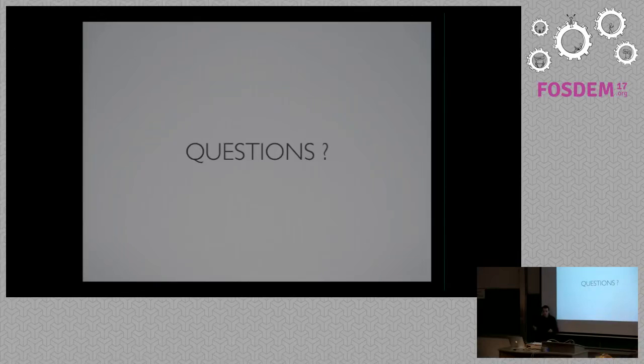So it's a completely software approach, and you can try to feed inputs and see what the outputs are. Or you can write a test bench to be sure that your design behaves correctly. And sometimes it behaves correctly on paper, we say, and when you program it, it doesn't work. And then it's not easy. Usually you have to add some circuit to try to understand what happens, and use the oscilloscope. But on this card, that is difficult.